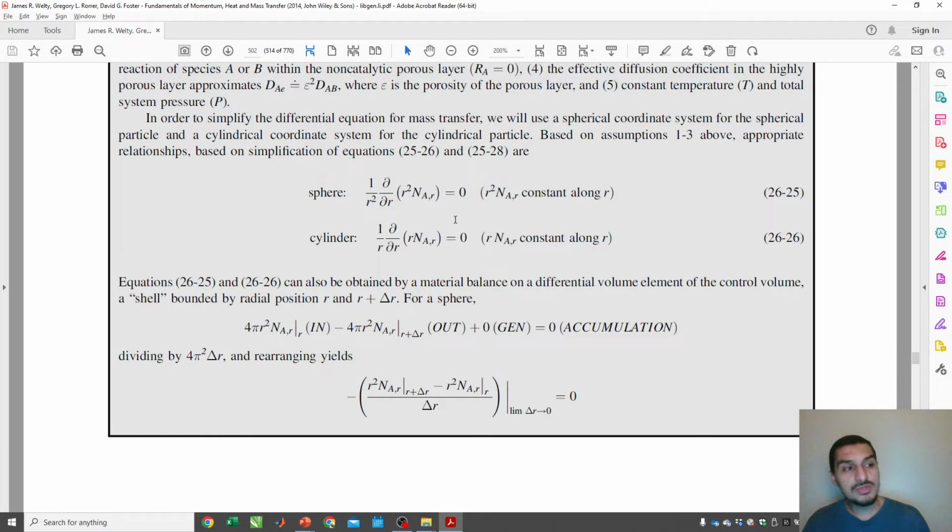So the other option that he suggested is to use a constant parameter, and the constant parameter is the rate. And if you think about this, if it's a steady state, then the number of moles going in is constant because it's a case of steady state. And for this constant rate, you will have decreasing area as you go from the big radius. As you go inside, the material is going into smaller area. So the flux would be larger. The rate is constant, the area is getting less, so the flux has to be higher. So this is very logical and very common sense.